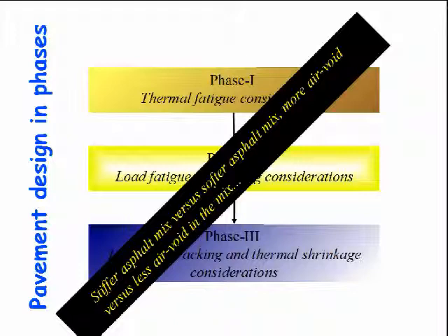But high stiffness bituminous mix is not always very good, because they tend to become brittle, and therefore their fatigue properties fall. And there are always conflicting criteria. Therefore, the idea is that let's not keep the mix design issues as a separate entity, where a mix designer designs the mix and then gives it to a pavement designer to design the pavement. There is a need that the mix design and the structural design issues are actually thought of combiningly.